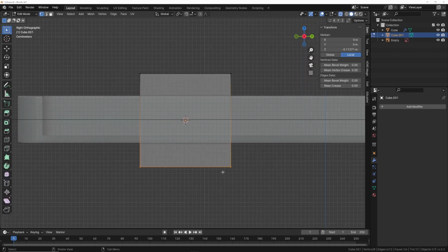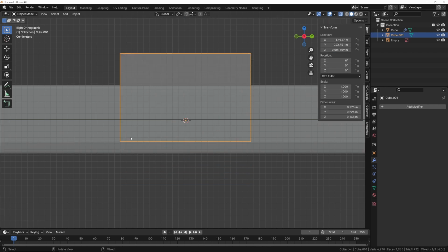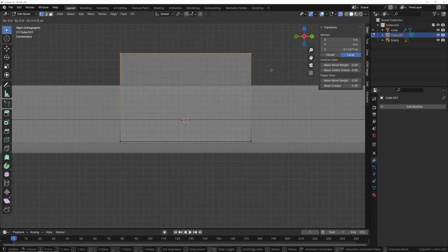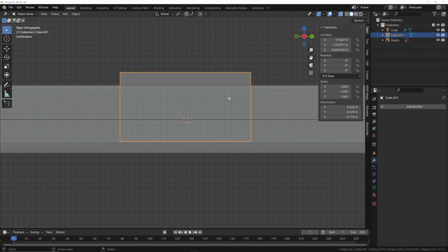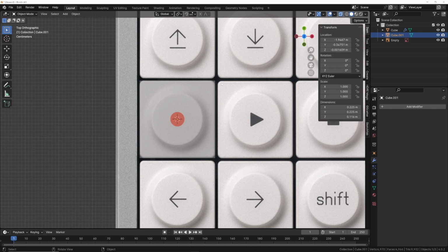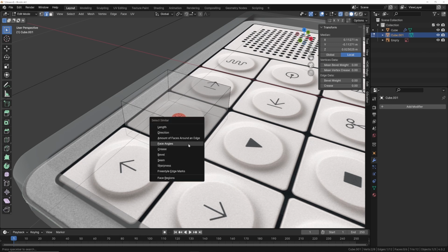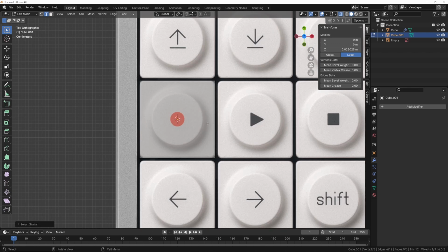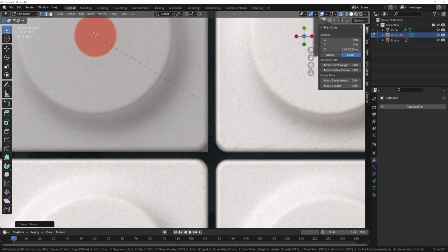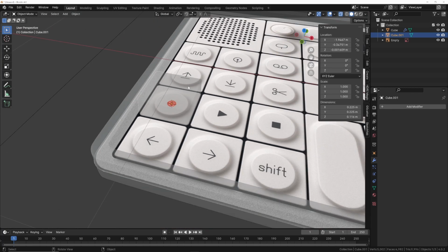And then I'm going to go into right hand view and I'm going to select these bottom vertices, just bring them up. I can see this line right in here, so I'm just going to move them up pretty close. And then we're just going to bring these down a little bit, something like that. And then we're going to go to the top view. We can see we're going to need these beveled edges here. So I'm going to select this guy, Shift G, similar direction, do the same trick we did before. Control B, bring those out, make that line up. That looks good.